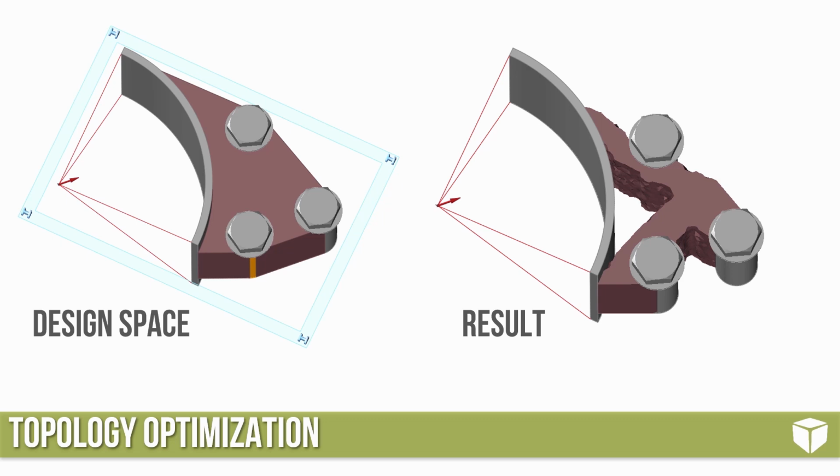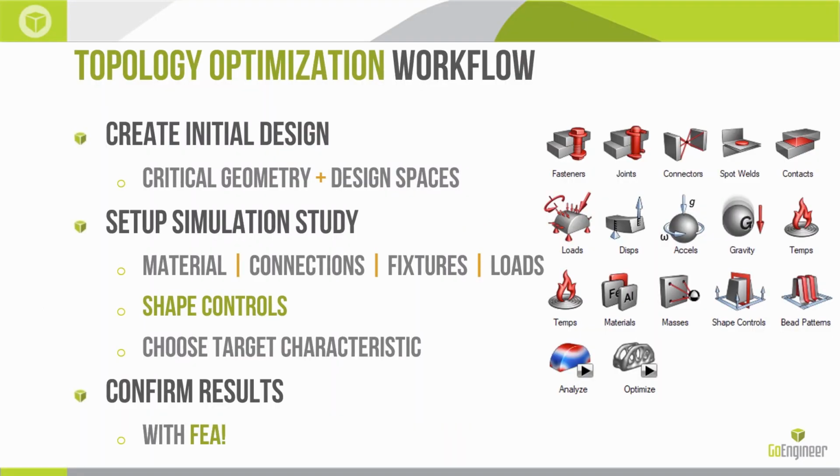In red, we have something called a design space. What we do is we model it up as the sort of maximum material condition for our part, okay? This would be the most material possible. And obviously this would be the strongest, it would be the stiffest, it would be all of that, but that doesn't make us a good designer to overbuild. We want a part that's nimble, that's lightweight, that is high performing, so we want to optimize it.